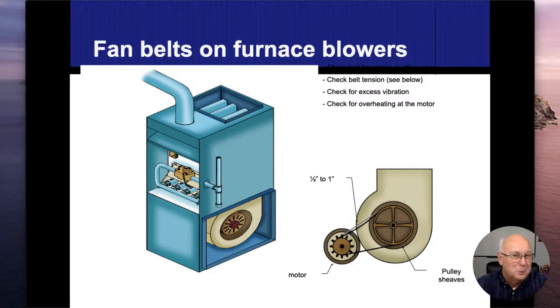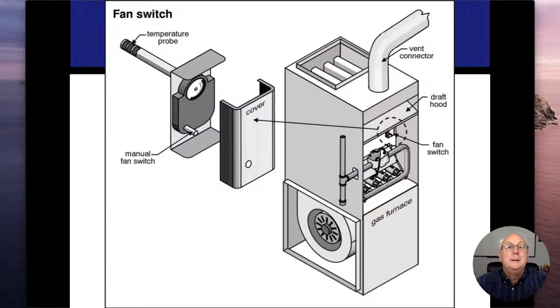And they're also multi-speed ones, or adjustable speeds. So you can actually program them on the computer by how much air it forces through the ductwork. And as I said earlier, cold air, harder to push, more fan speed. These belt-driven ones, they were one speed only. So when we start getting into our forced air furnaces now, we need to start learning the different parts that we're going to be finding inside the furnace.